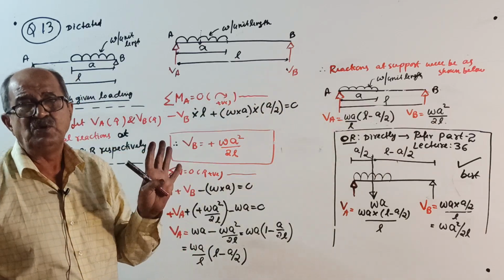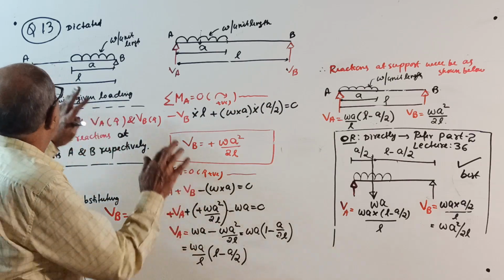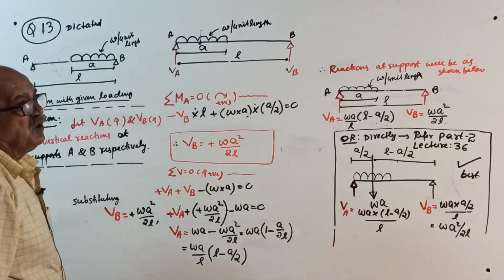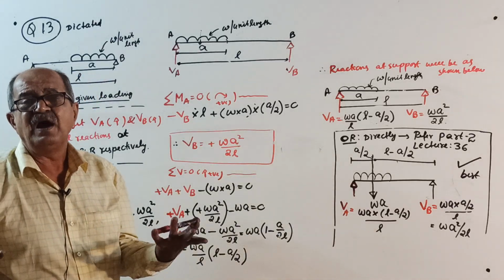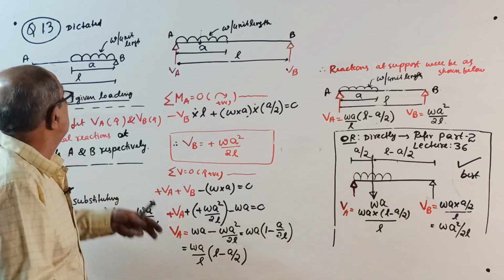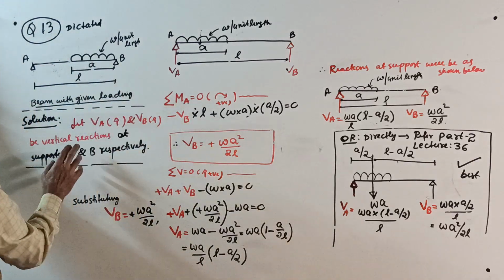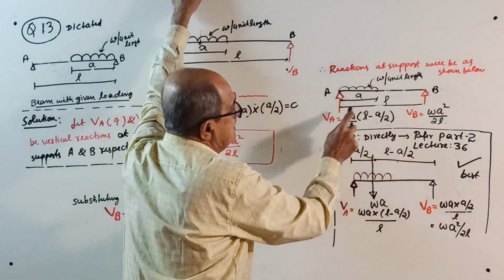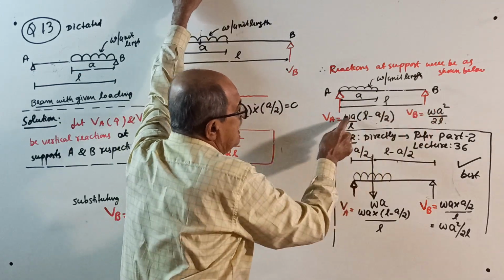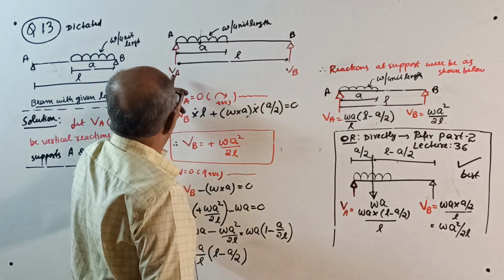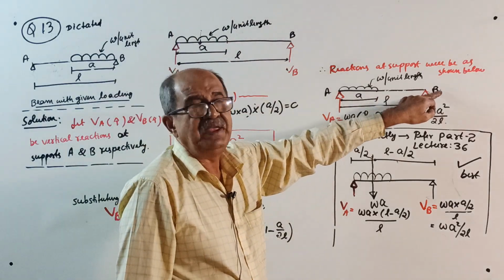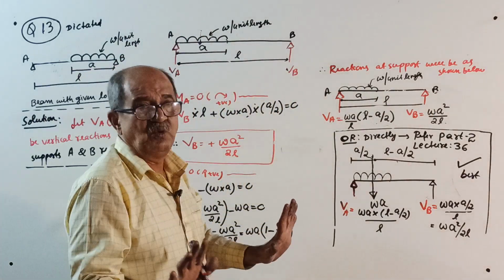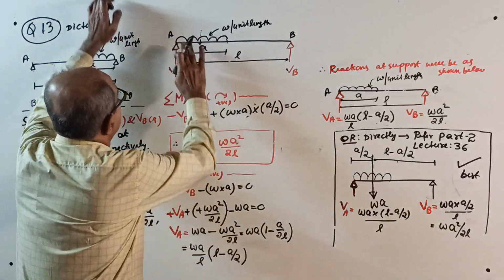So everything I told, I am systematically doing. Remember, now here there is no idea whether A is more than L by 2 or less than L by 2. It can be any length. Okay, WA over. Now guaranteed, this reaction will go there, that will come here. What last time you got as VA, now will come as VB. What last time you got as VB, now you will get as VA. Guaranteed. Okay, we will see. Okay, start. Fresh sketch.